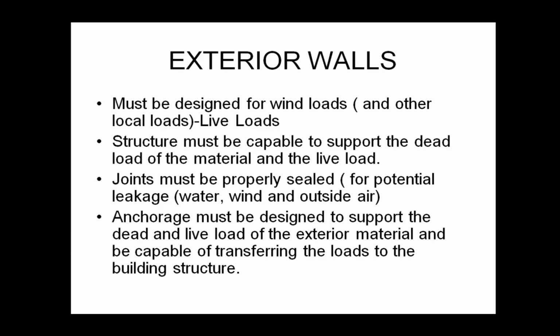Again, just like with the roofing material, anywhere you have a joint or a break or a change in materials, from wood to brick, or brick to the windows, or whatever the difference is, wherever you have those joints, those are the most critical areas to keep sealed, because generally they're the first areas where you have water or wind intrusion. And again, as part of the design, any anchorages, connections, however you're fastening this material to your building or to the other portions of the wall, those have to be designed to support all the weights, both live loads and dead loads.